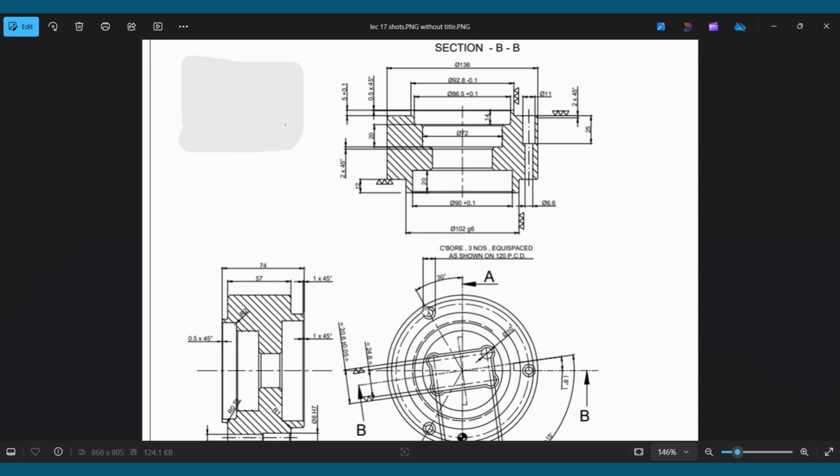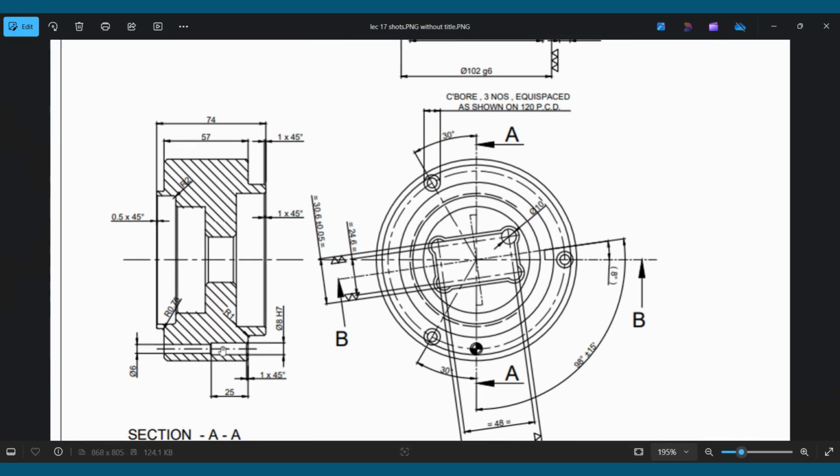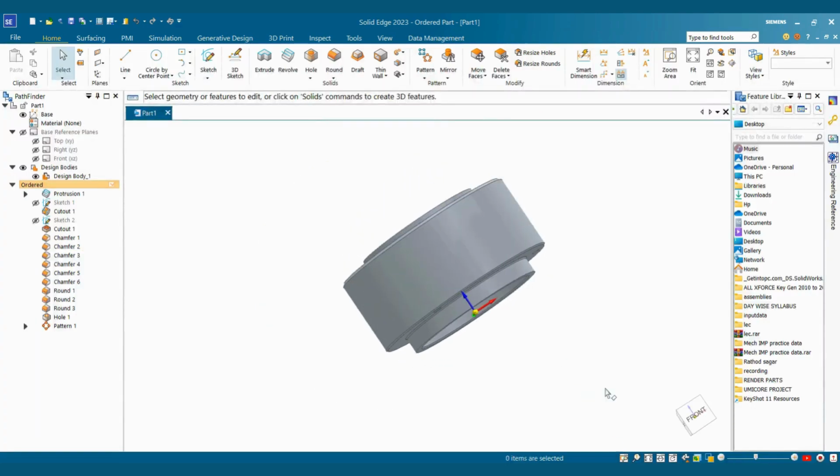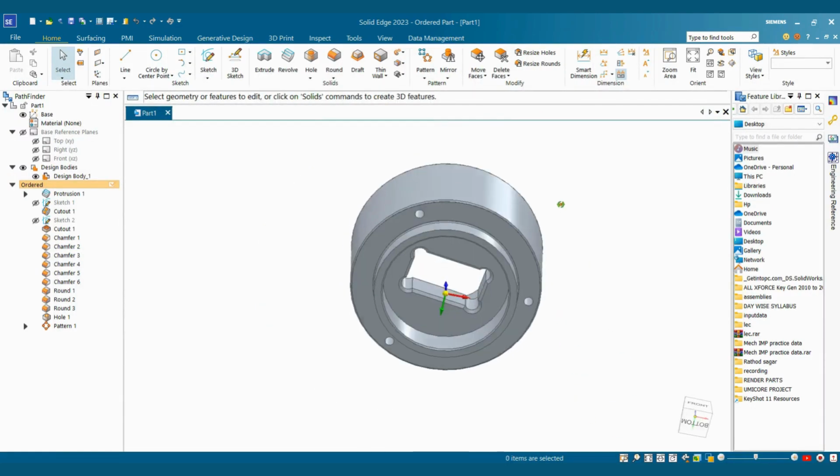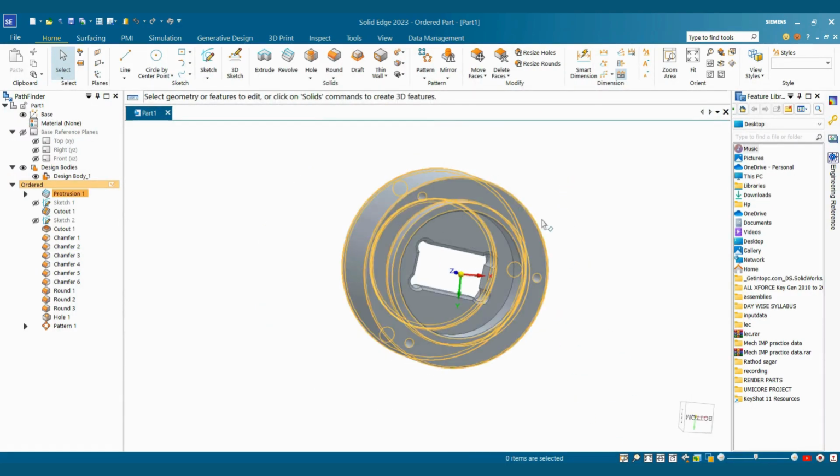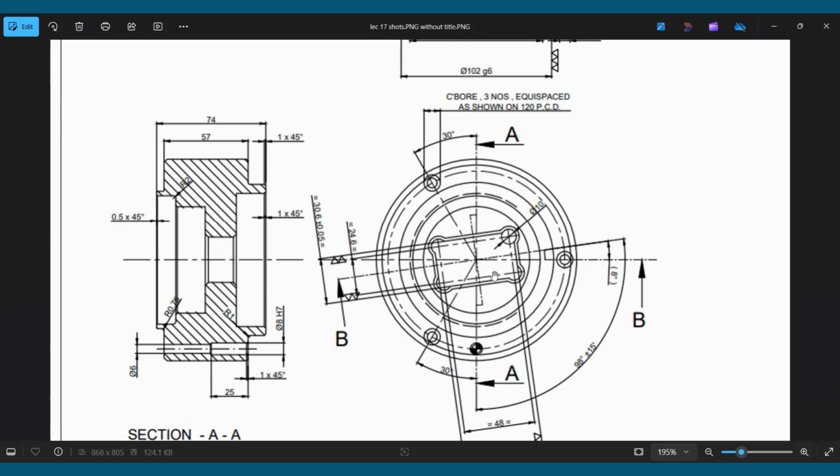Lastly we are going to make these two holes that are dowel holes from the bottom side having depth 25 and diameter as 8 with the fitment of H7. The depth is 25. Now this dowel hole will come on the same PCD distance, that is of 120. So at the bottom side we require the hole and it is coming at the center here. You can see this section AA, this circular profile quadrant center is coming here at vertical center.